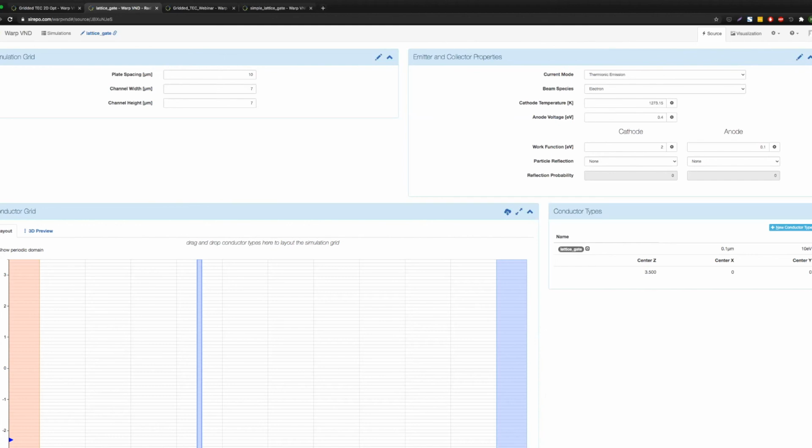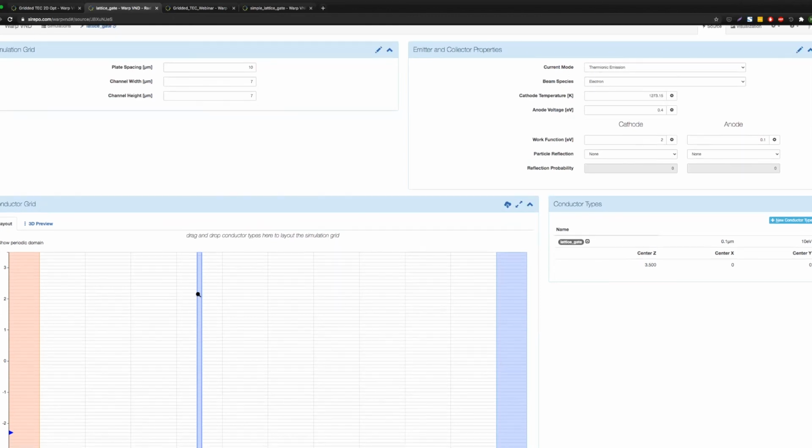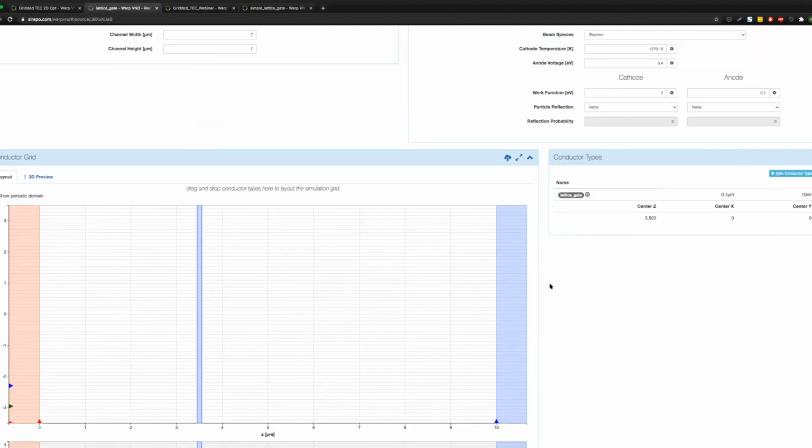Yeah, so the second question was, could you have made the simulation domain half as tall and obtained the same results? I assume with the 2D. Yes, so you can vary this transverse domain size quite significantly and obtain effectively equivalent results, essentially because there's periodic boundary conditions on the domain. The code operates as if the same emission current density is happening outside of the domain, to the left or to the above and below it. So you can definitely reduce the domain size.